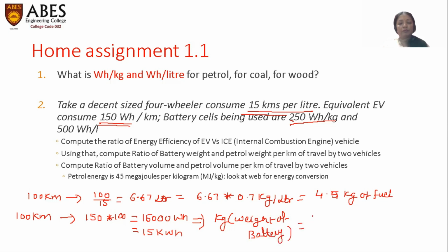So battery weight would be 15000 divided by 250 watt hours per kilogram. So it becomes 60 kg.